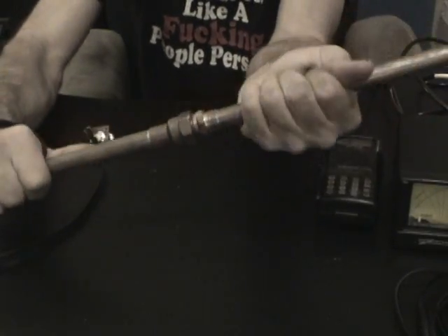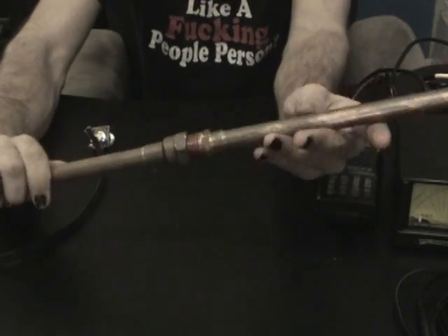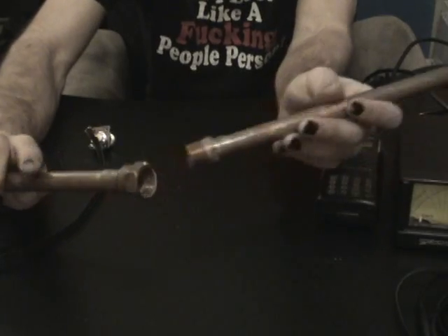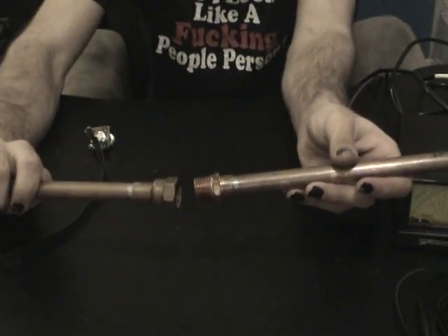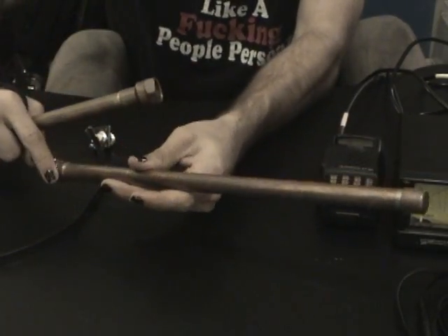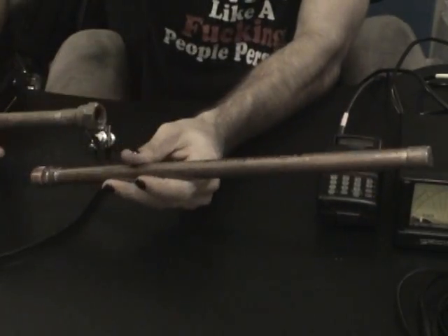Now, if you are going to be designing this antenna for something that's going to be excessively large, and you want it to be something that you can either throw in the trunk of your car or inside of a backpack or a small bag, use these threaded adapters. Just remember that these threaded adapters will elongate the size of the copper pipe, so you will have to go and cut the tips of your pipes down a little bit smaller.